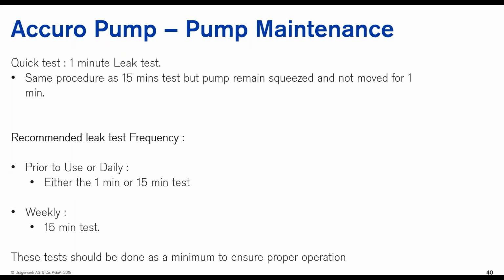So what is the recommendation in terms of frequency? For example, prior to use or on a daily basis, and let's say if you are going to take measurements very frequently, and also you don't want to take too much time, you can actually do the 1 minute leak test. So the 1 minute leak test is the same procedure as a 15 minute test, just that the pump must remain squeezed and not move for 1 minute.